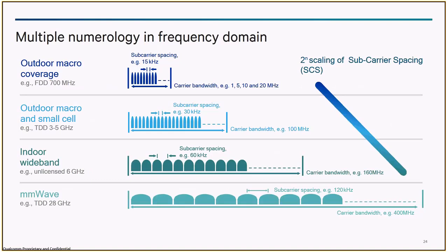Within the 1 millisecond, uplink and downlink are both there, TDD is the same as in LTE. How can you decode and respond in the same slot? You're saying mini slots. Now 1 millisecond has 7 slots, so you get some additional timing. Within that 1 millisecond, approximately 600 microseconds, the first 2 mini slots you will be done with receiving, and maybe last you would get a PDCCH grant, you decoded your PDSCH, and you have sent an ACK/NACK as well for that PDSCH.